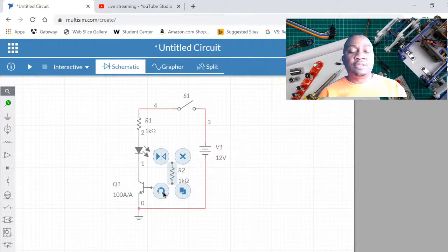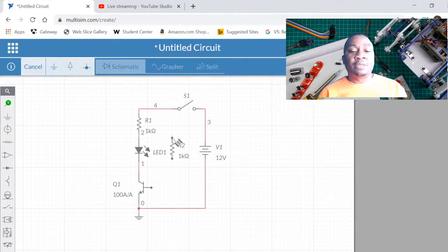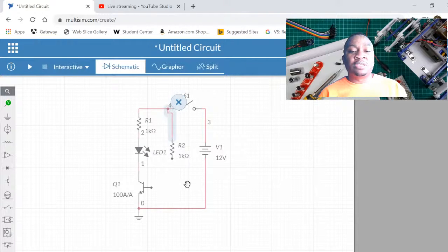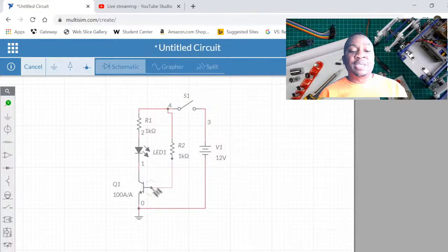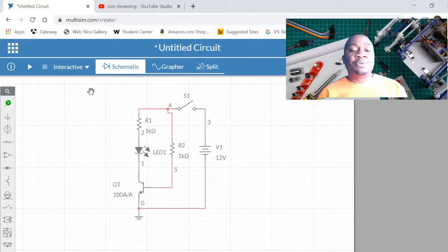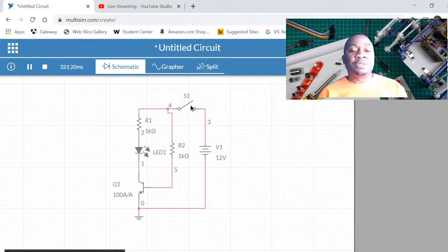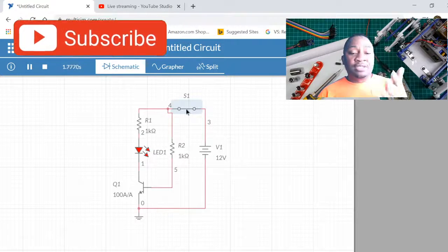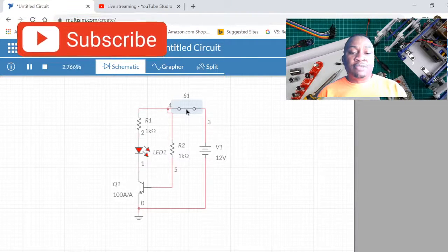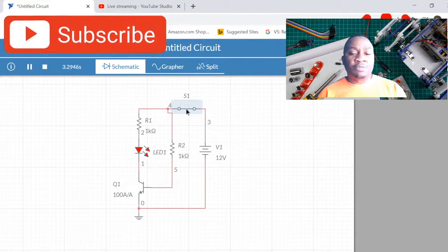So let's just put this somewhere here and pull it up. To pull up simply means just sending it to the positive rail, right? If it is PNP, you're going to be pulling down, right? So pull up for NPN, pull down for PNP. So let's turn this on and flip our switch on, and the LED is on. Off, on, off, on. Simple circuit. So you have a transistor, an LED, and two resistors, and you have all you need, right? This circuit works fine, perfect.